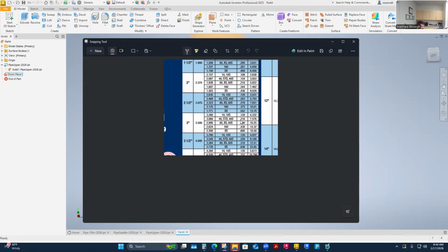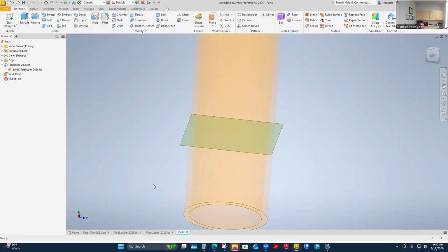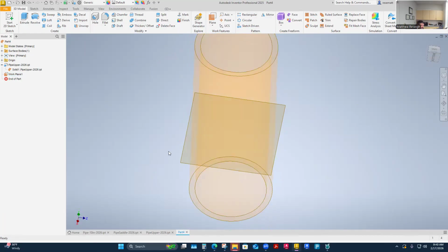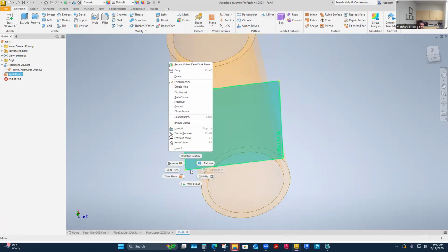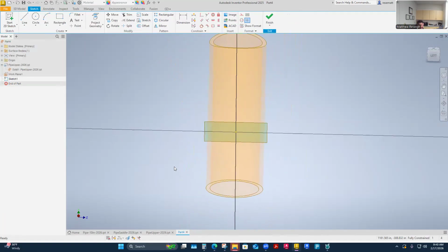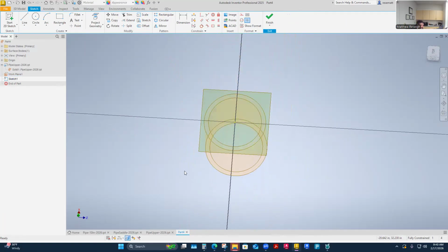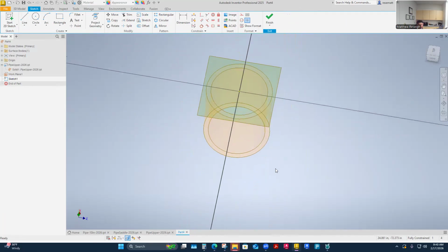So I'm going to draw a 0.216 wall thickness on a 3.5 inch. Those will be my offsets. From this, I'm going to work from this plane right here. It's kind of the bottom side of it, but that's okay. I'm just going to say sketch here, new sketch. It might flip my part around a little bit, so I just need to identify, oh yeah, here I'm extruding this way down. I can cut to that plane, F7 slice graphics, right? So there I am on my plane.